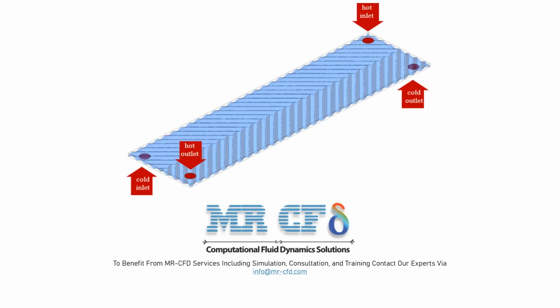The three-dimensional geometry of the present model is designed by Design Modeler software. Since the model is related to the plate type heat exchanger, it consists of two main parts: hot water flow zone and cold water flow zone. The boundary between these two flow paths is determined by the separator plates or chevron.